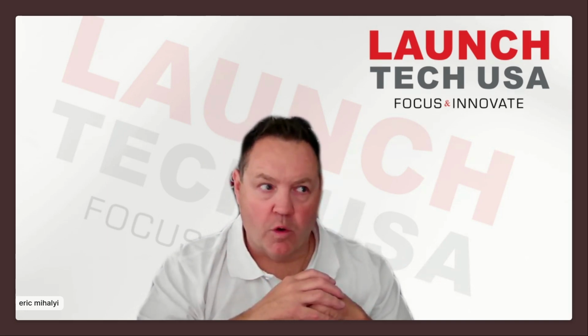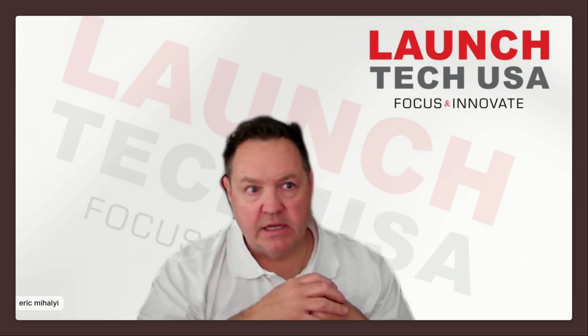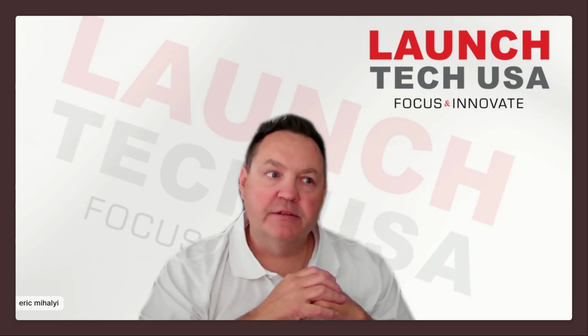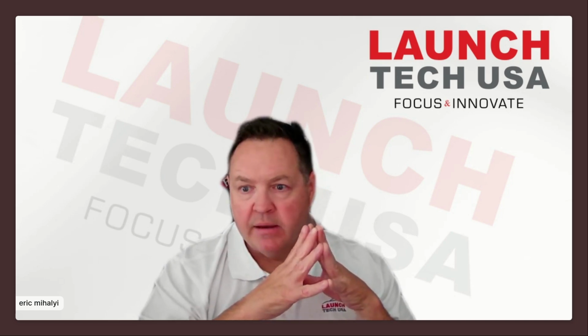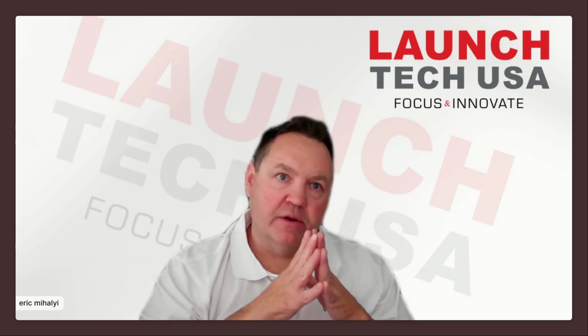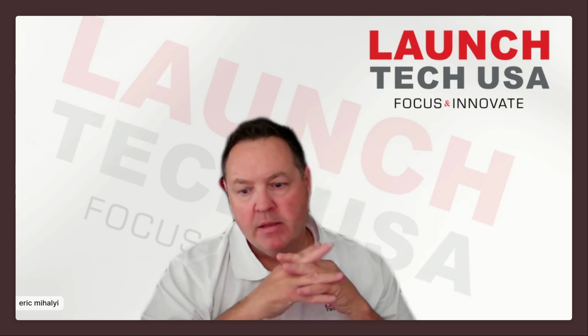If you're working on a Ford or some of the models that have built-in power balance tests, go right into that. See if I find, no, look, cylinder 7 is my problem here. So then maybe you do an actual manual compression test, right? And it just gets you into the area that you need to be for diagnostics as fast as you possibly can without chasing your tail.